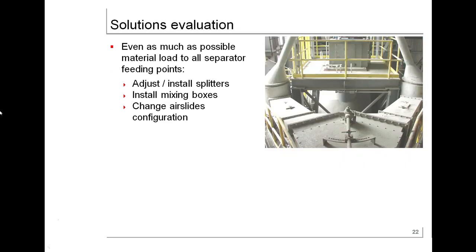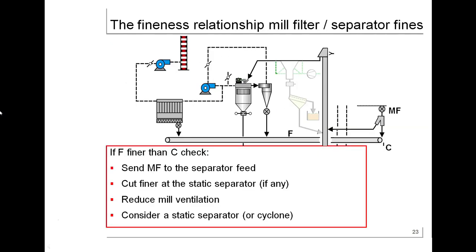Solutions evaluation: load material as evenly as possible to all separator feeding points, adjust, install mixing boxes, change air slides configuration. The fineness relationship of the separator fines: if F is finer than C, you can check the points mentioned below.